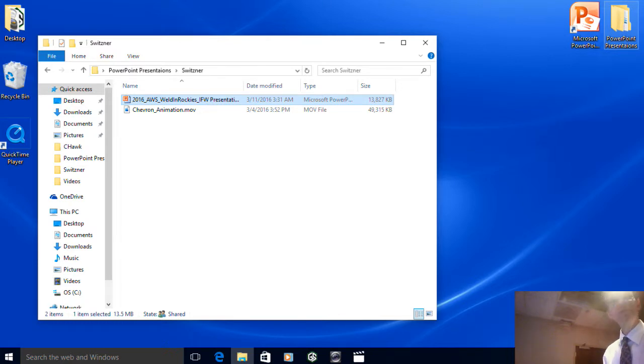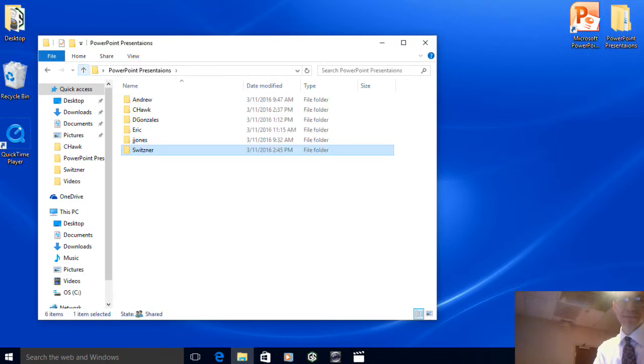Okay. Yeah. It's usually big. It's like usually big mixing ranges. It says you got to meet these mechanical properties, but you also have to stay within a certain range of chemistry. Yeah. Whereas if you look at 304 on the AISI side, you get very narrow ranges of allowable chemistry variations.